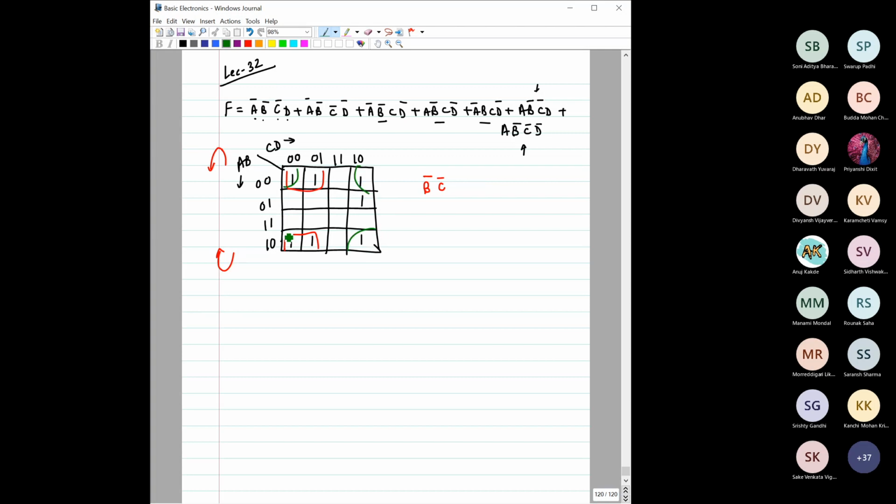Right? Okay. Other thing that we can do, you can see at all four corners we have ones. Again, the Karnaugh map is very foldable from both sides, right? So if you fold it carefully, you can attach all these corners, and make a group of all these four ones, right?